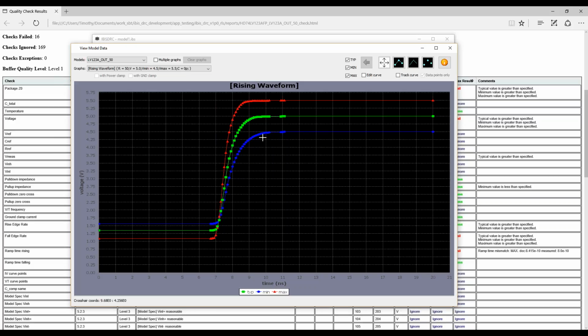You just want to grab the transition, and when it reaches steady state, you want to cut it off as much as you can. Because remember, this time in an IBIS model, the transition internally always gets subtracted out of a flight time delay. And if you make it too long, then you can get into an overclock situation where if you want to switch at, say, half this frequency, it'll be right here, and then it wants to transition from a high to low.